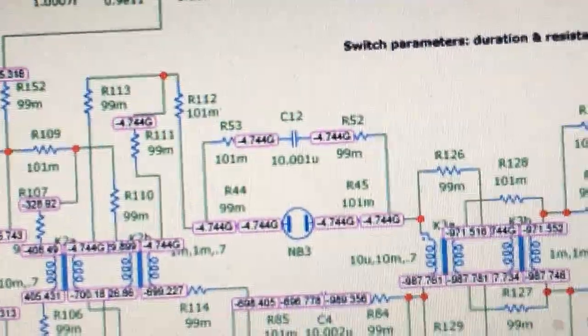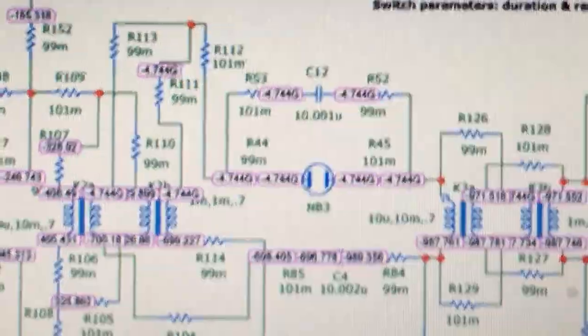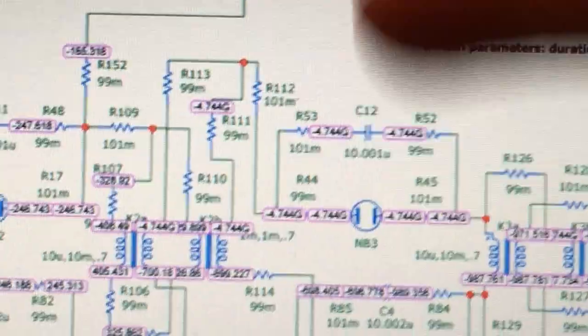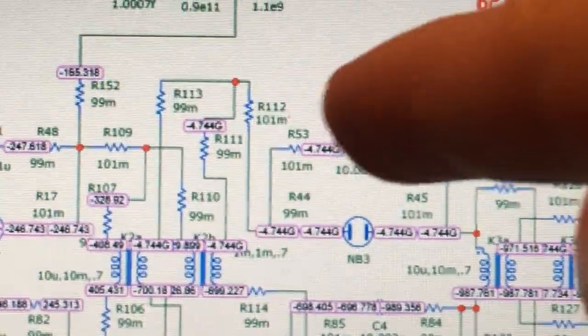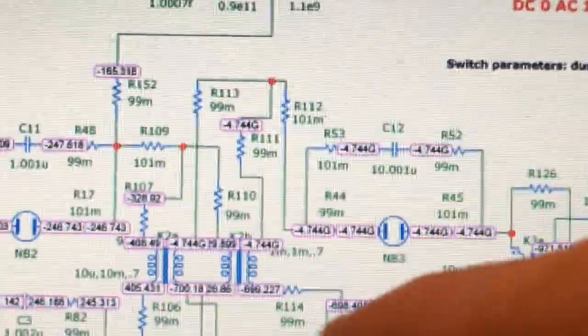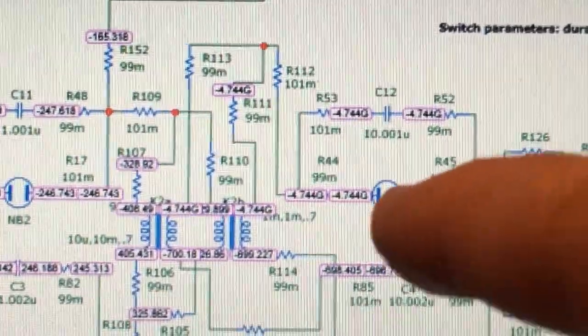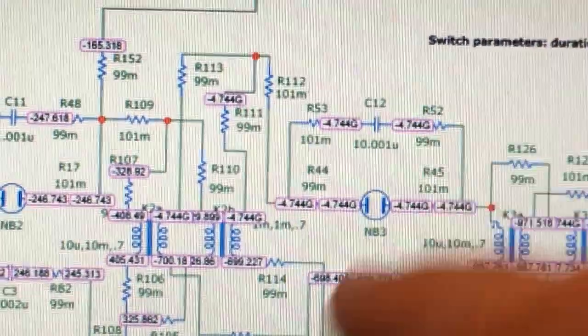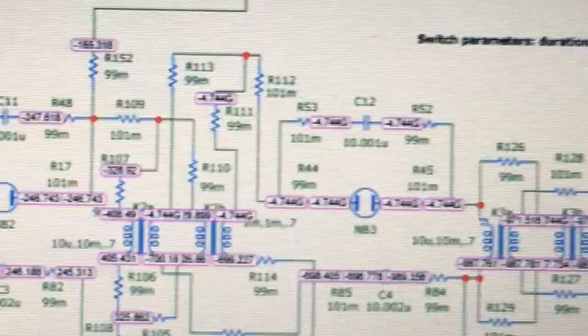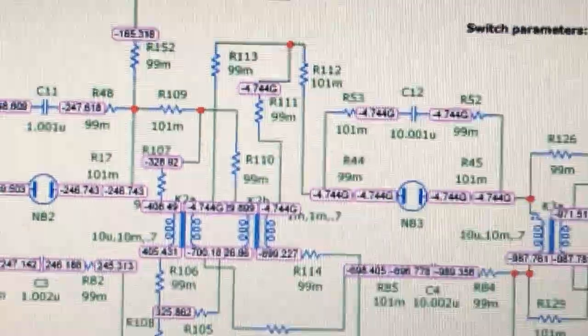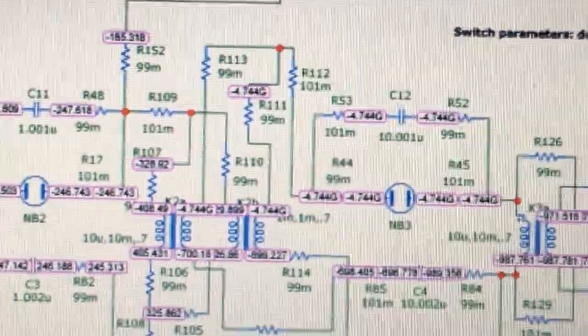So what I've learned to do in LTSpice, if they force me with a fatal error message, is I don't use a resistor between the circuit and ground. I use a capacitor of 10 picofarads, and that actually boosts my voltage buildup and prevents it from bleeding out because I'm using an oscillating circuit. The blocking capacitor of 10 picofarads, a low capacitance value, is perfect for